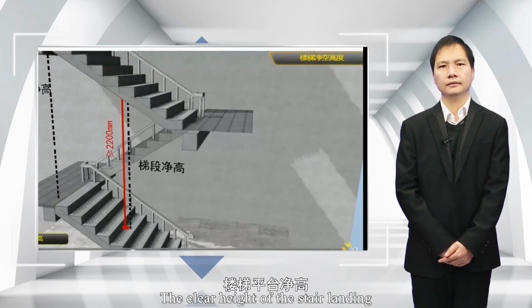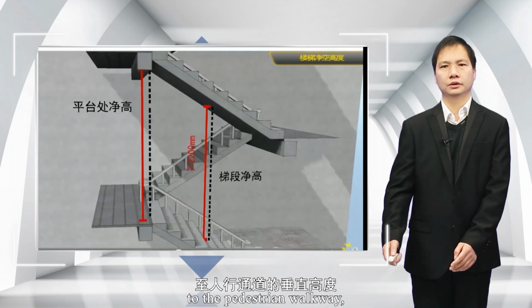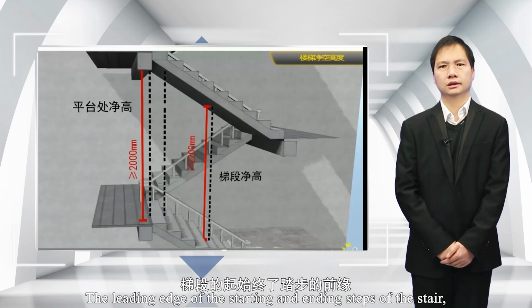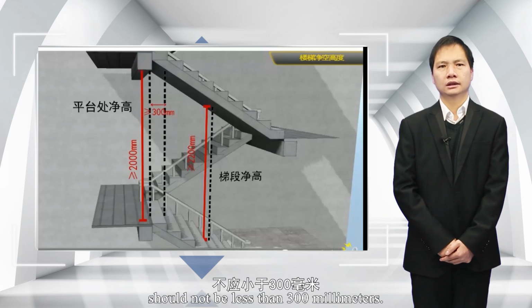The clear height of the stair landing is the vertical height from the lower edge of the platform structure to the pedestrian walkway, which should not be less than 2000 millimeters. The distance between the leading edge of the starting and ending steps of the stair and the outer edge of the protrusion should not be less than 300 millimeters.